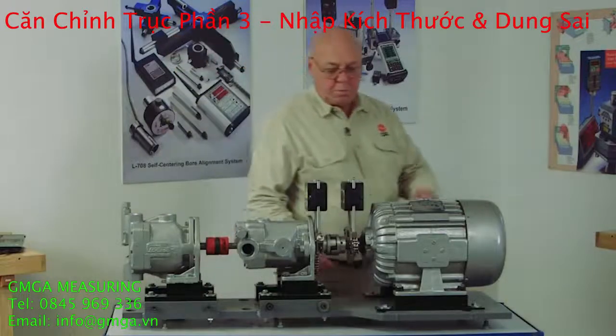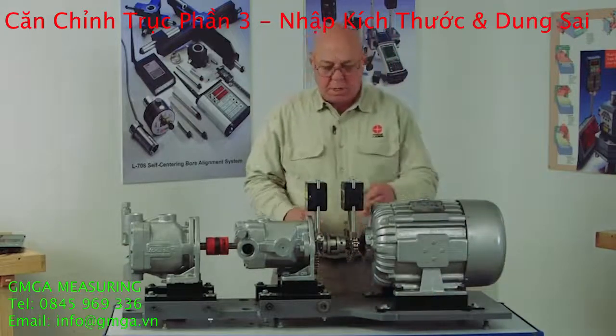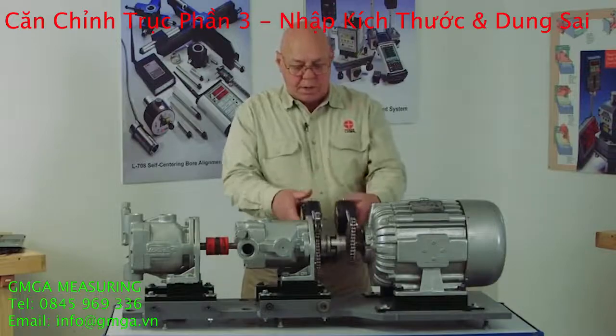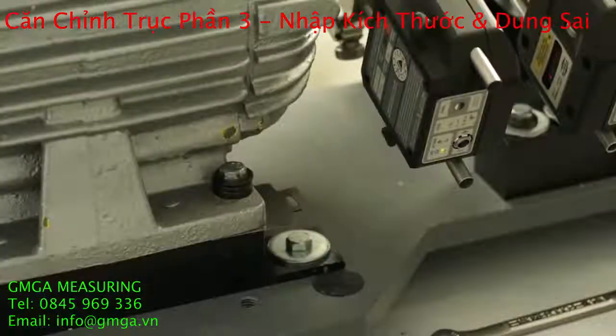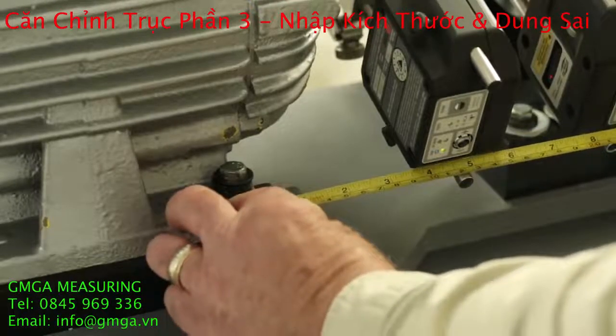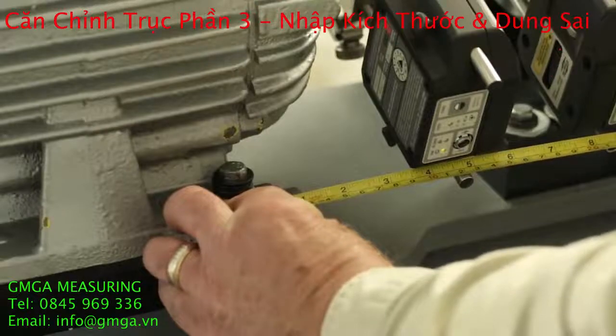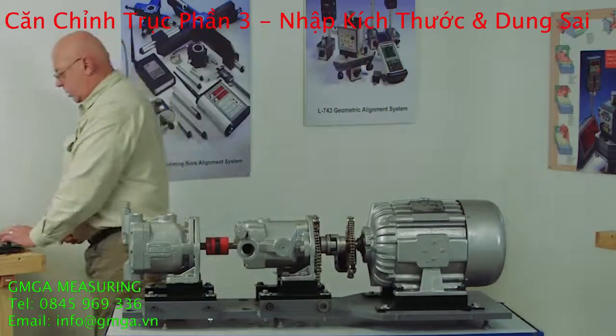The first bolt would be, in this case, right here, or up here on this side. So the way I do it is I know it's 2 inches from here to here. I'm going to measure from this post to that bolt and add 2 inches to it. That just makes it a little easier. So we're at 4 3/4, so 6 3/4, 6.75.